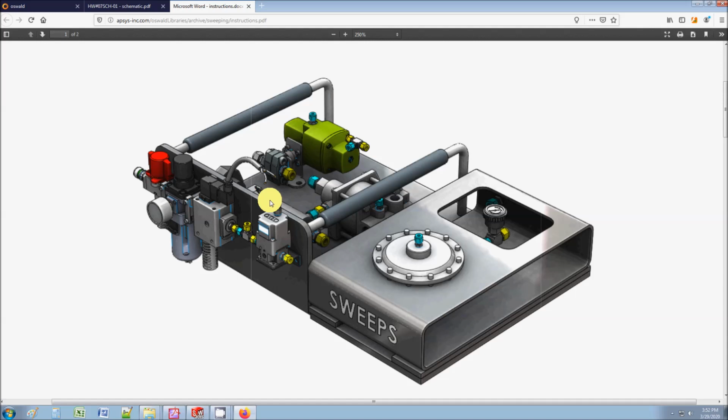Okay, usually you don't use digital signals for this because you need variation. So you have to use an analog signal from the current through the EP regulator. But anyways, what I really like about these is that you can just type in 50 psi, 75 psi, and this increments. The readout is like perfect. It's like 60 psi, 70 psi. So I really like that, as opposed to these regulators where you modify them with your hand, it jumps up and down and it's very difficult to control. So I really like these.